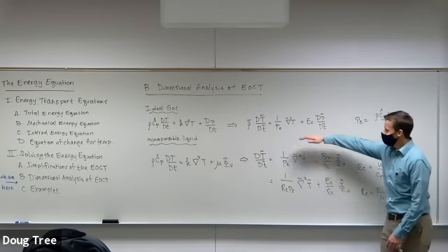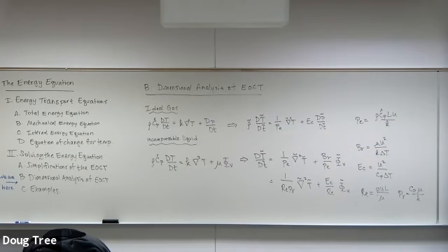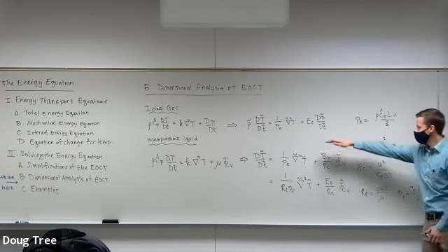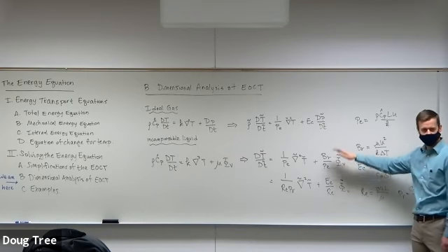But so we can look at the ideal gas one, and you end up with a Peclet number and an Eckert number. The Peclet number, you remember, was this ratio of convection to diffusion, or convection to conduction. You can maybe remember that because the conduction is at the bottom. And then the Eckert number was this guy here, which was the ratio of kinetic energy to enthalpy. We have the Brinkman number, which was basically the relationship to viscous dissipation. You can think of that as mu u squared over L squared divided by, this was conduction. And so we had to divide it by the Peclet number to get the convection.